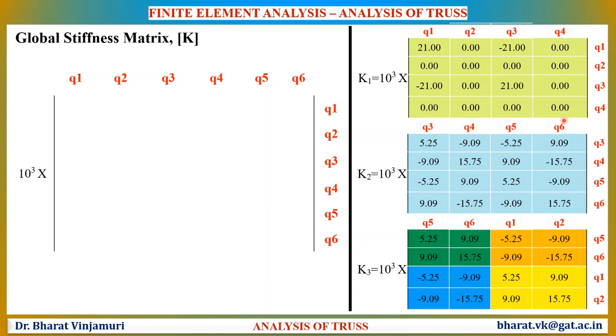The top ones, as I said, are the columns, and the right side displacement vectors represent the rows of a matrix. Also, the matrix K3 is in between the following displacement vectors: Q5, Q6, Q1 and Q2. The order of these displacement vectors plays a very important role.